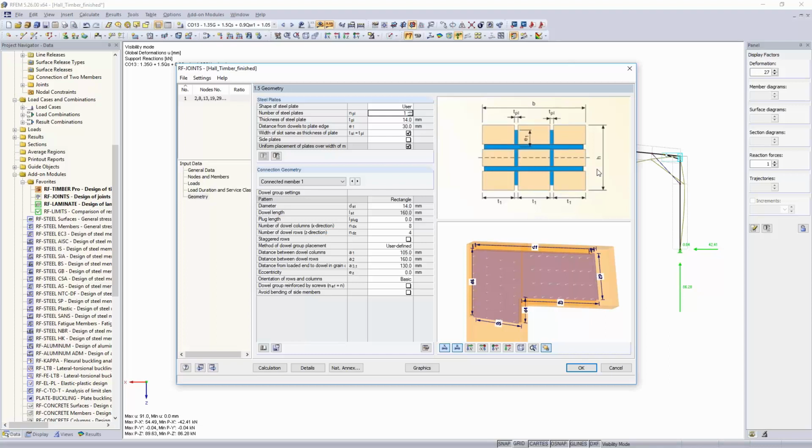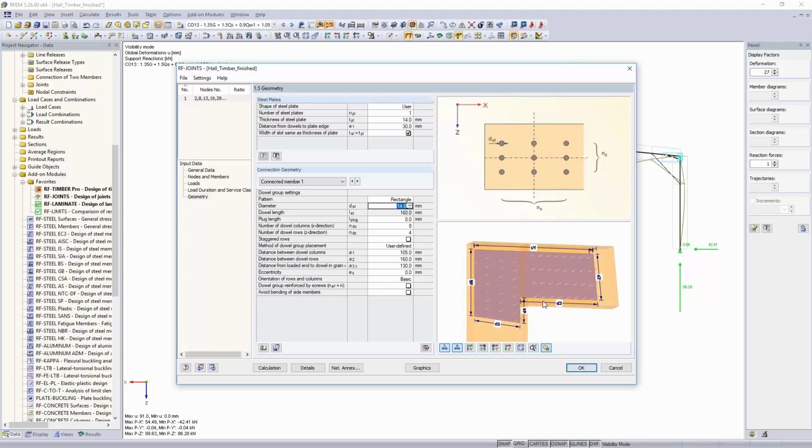Usually when you calculate with this slip in the connection, you have a lower loading of the timber, but a higher loading of the connections. That's what you really will find out. But the steel plate was only loaded 7%, so 2 plates probably make no sense in here. And therefore I changed that to 1 plate because I think it's still enough.